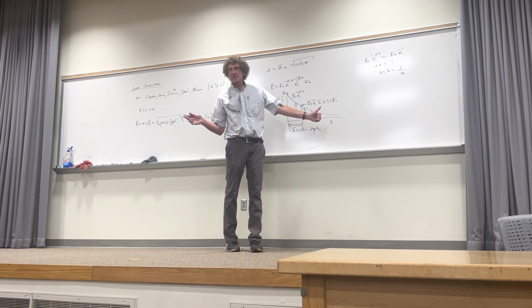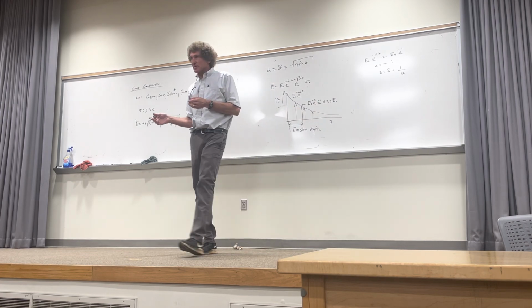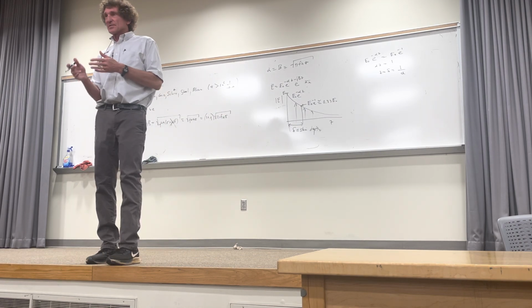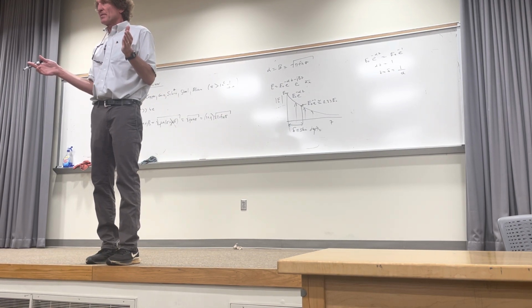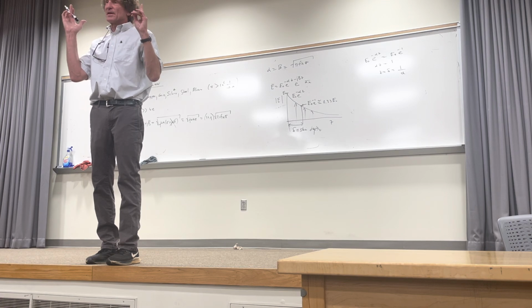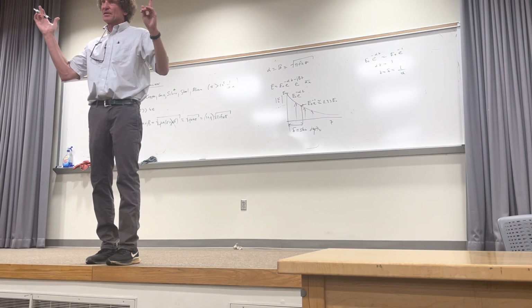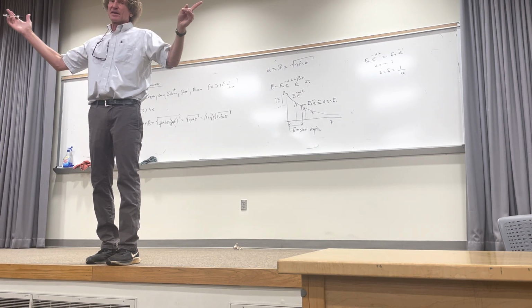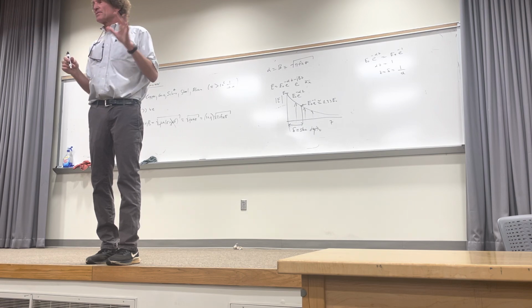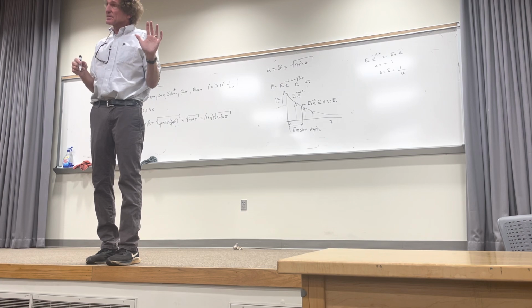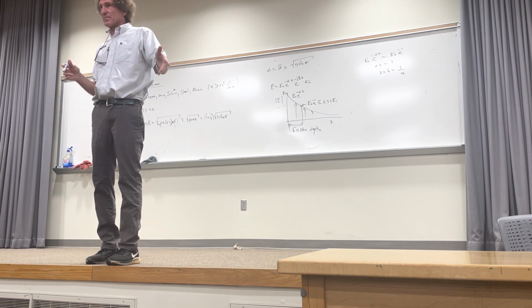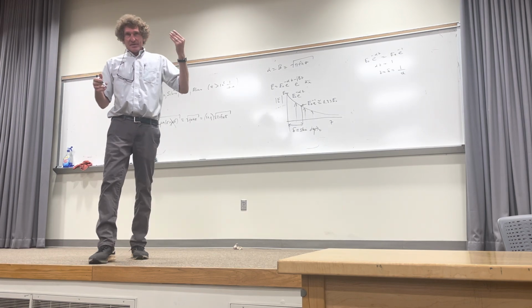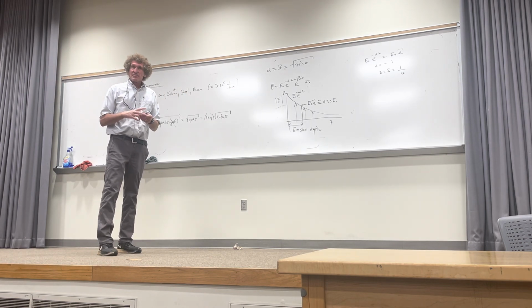And that should make sense to you, because you remember, I forgot if you got this in your statistics course, they talk about the standard deviation, right? If you're within 1 standard deviation, you're 68%, 2 standard deviations, I forgot, it was 95. Anyway, it keeps going. Well, with the rule of thumb with skin depths, if you're 5 skin depths into a material, the signal is considered gone, by any measure. All right, there is something there, but it's such a minimal signal strength you don't have to worry about it.